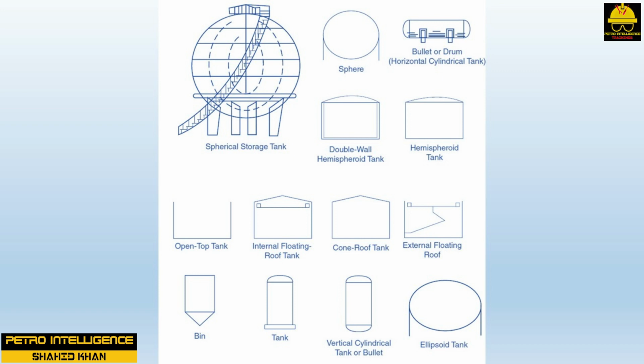In the basic design, a void forms between the floating roof and the product, forming a constant seal. The primary purposes of a floating roof are to reduce vapor losses and to contain stored fluids. In areas of heavy snowfall, an internal floating roof is used with an external roof because the weight of the snow would affect the seal.